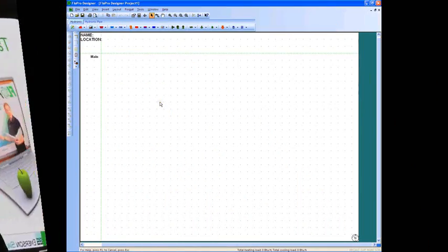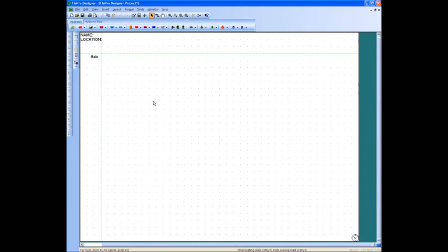Start again. So here we are at the screen that you're going to see when you start your drawing. We're going to have a blank template here. So we'll go up, we're going to create our building, so we'll go up here and click on this little icon that says wall, and we left click on that, and you'll see that the cursor now turns into a pencil, and we have some red lines, and we want to superimpose the red line over the green line, and that becomes our starting point.